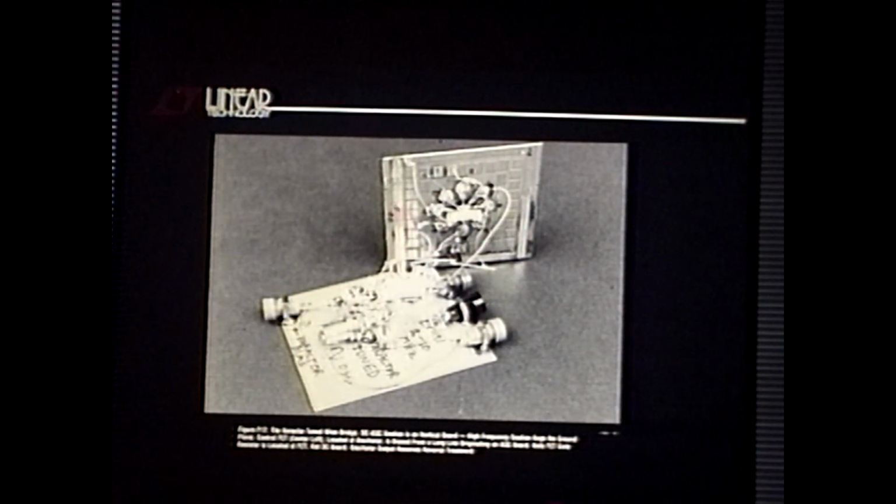I tacked the ground strip on this breadboard to the copper clad on the fast guy now, and all the wideband stuff is tight around the output connector. But I can bring in the DC signals. There's a resistor here. So this side of the resistor, this is the AGC output here. This side of the resistor, that may be crucial in terms of speed. So I'll keep my lead length long on that side of the resistor, and the inputs are done the same way.